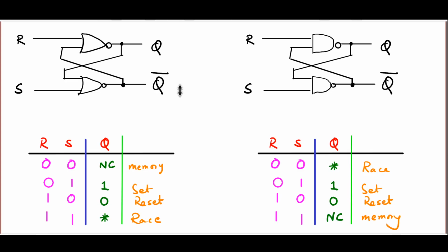This is the case that you would want to avoid simply because once again when the inputs went back to their resting or natural state, which is both 1s, then the output cannot stay 1, 1. It has to change to 1, 0 or 0, 1, but which one actually occurs depends on which of the two NAND gates is faster or which of the two inputs R and S went to 1 earlier. So let me stress once again that this is the situation that you would want to avoid. And of course you would want to design more advanced latches where this race condition would not occur.